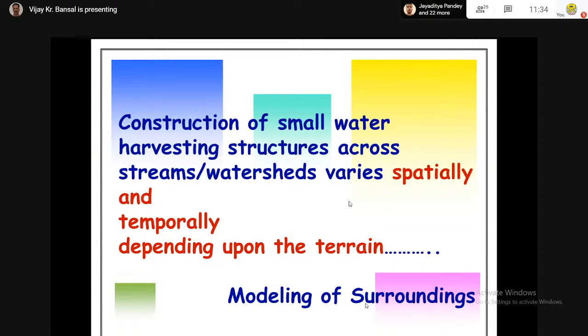Okay. I repeat again, in the topography modeling, we have two steps: modeling of existing facilities, utility which lies on the surface, and modeling of surface. Okay. Just to model surface, first step is survey with the total station. Data from the total station was transferred to Leica CAD. Then after this, the data goes to AutoCAD, and from AutoCAD that data was transferred to ArcGIS as a geodatabase.